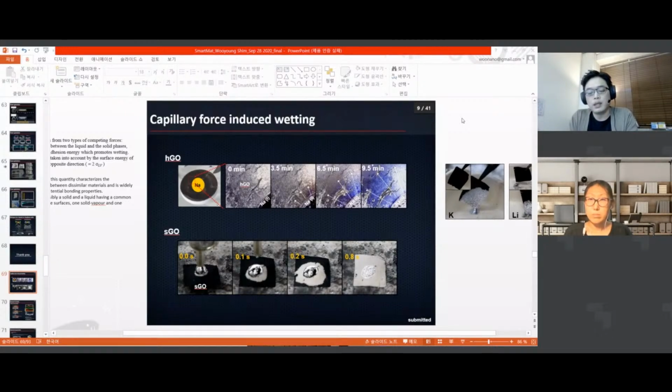So in order to improve the resolution in a light-based technique, you need to care about the wavelengths and also distance and also enhancement factors. These enhancement factors contain the quality of the photoresist. For example, if you want to increase the resolution, you need to decrease the height of your photoresist. Okay, so that's the one issue.